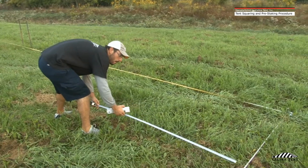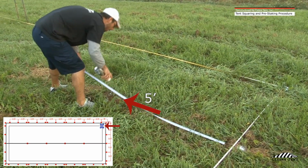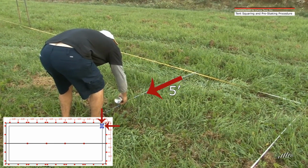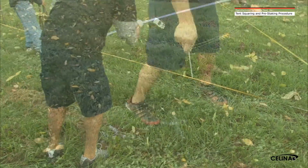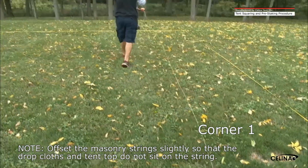Once the stake locations of the tent are marked, measure in 5 foot from each corner to set the perimeter of the tent. Stretch a masonry string around the perimeter of the tent to signify the tent top location.